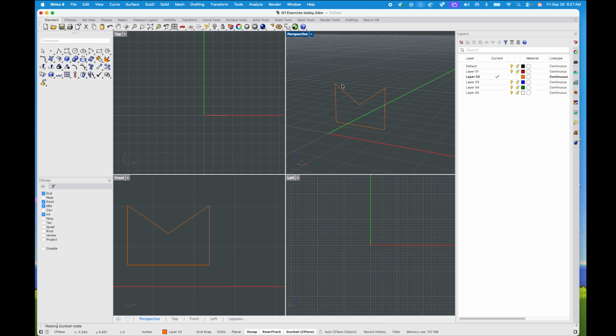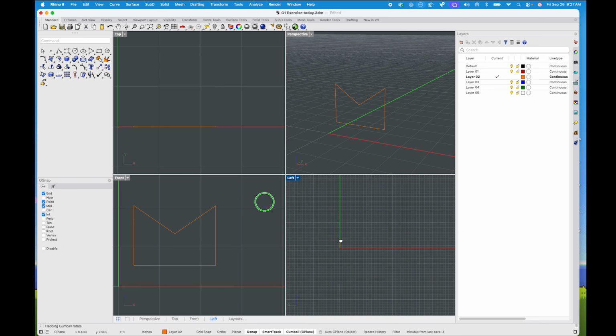However, for us, we know that this object has a thickness, so let's go ahead and match that. You know, here's our top view. Here's that front view. And you'll see that so far we don't really have a side view yet. Again, that is also what's missing in our diagram, right? But we're kind of building it from the views itself, right? So we've joined this object, or sorry, I needed to go back one more. So join it, right? The next thing to write down is extrude curve, right?